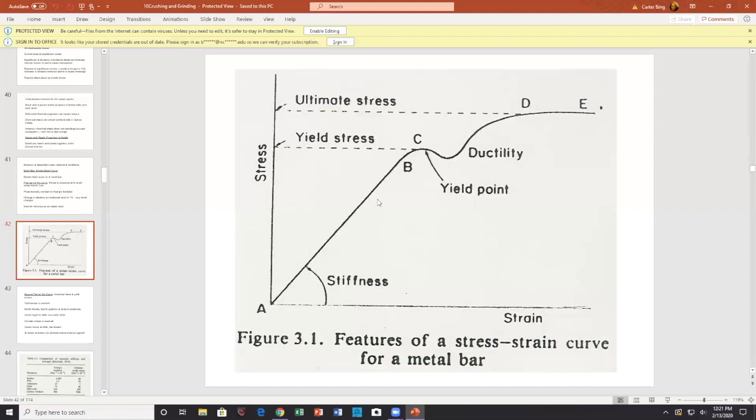So not only do you want to measure the particle size of the feed and the particle size of the product, you also want to measure the temperature of the feed and the temperature of the product. And you have the mass flow rate, the temperature rise, the heat capacity. You get a measure of how much energy was wasted in not breaking the material. So that would be an interesting calculation you would do. Mass flow rate times heat capacity times the temperature rise.